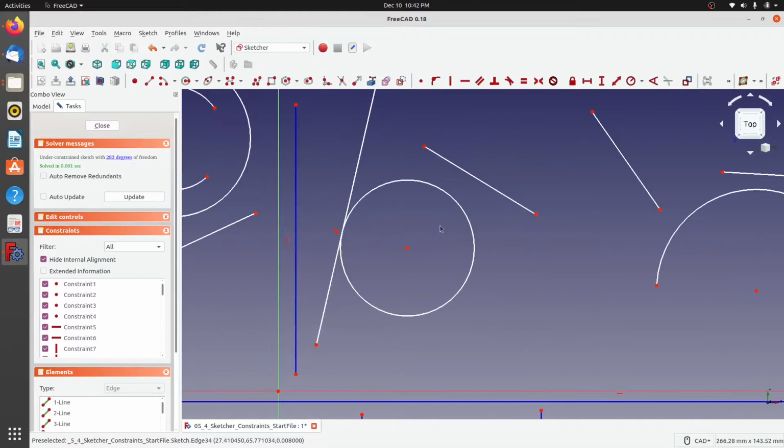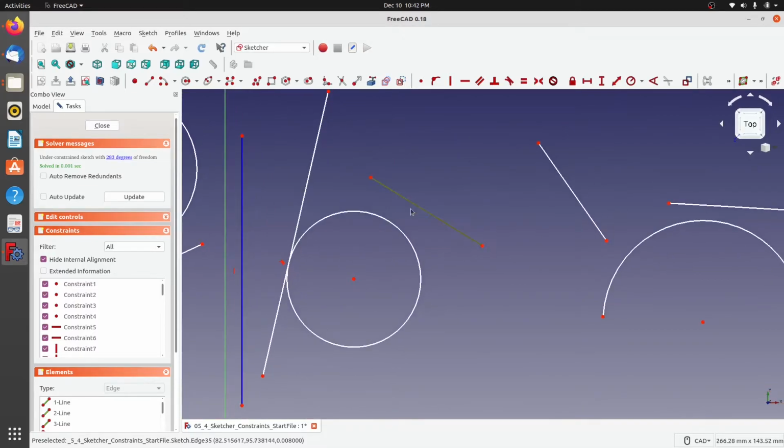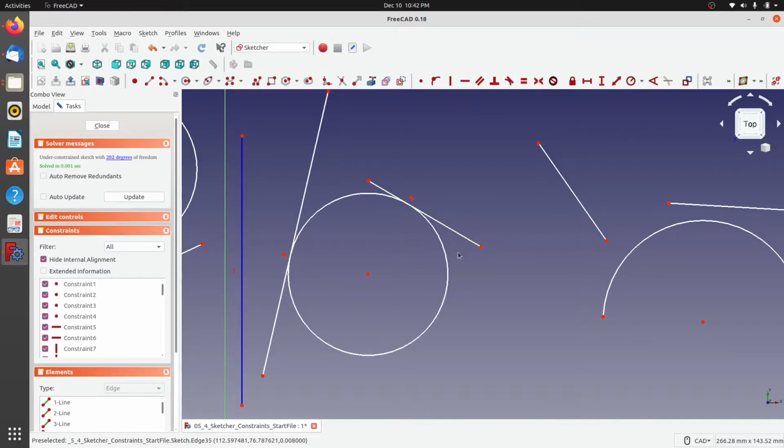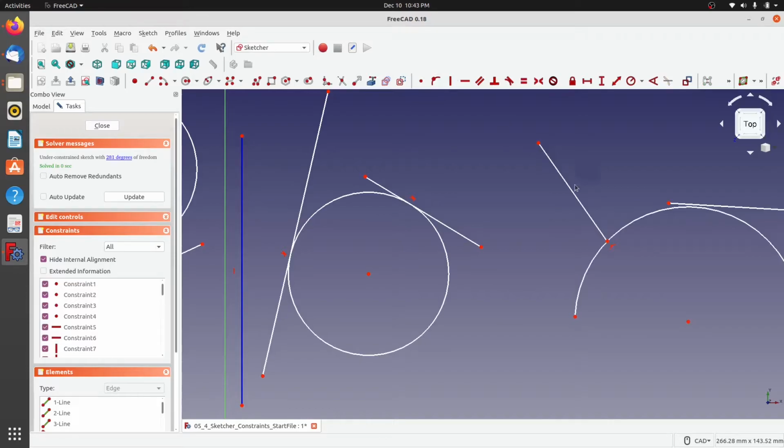Now the same tangential constraint can be connected between several different entities. So you're not just limited to one, you can create that tangential constraint to several different entities. The way in which we can do it is to make this point on this arc by clicking on this and then making this line tangent to this. Will it work?